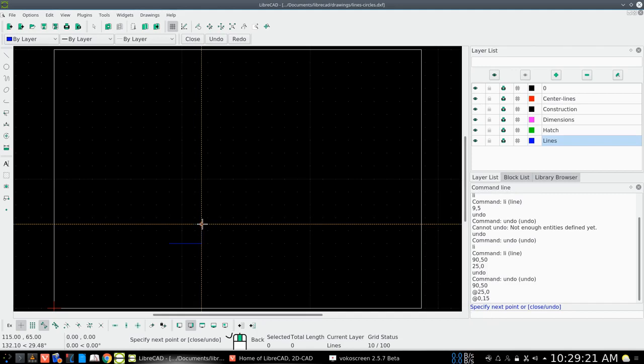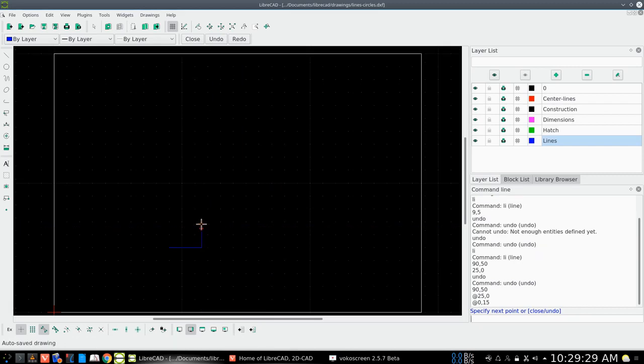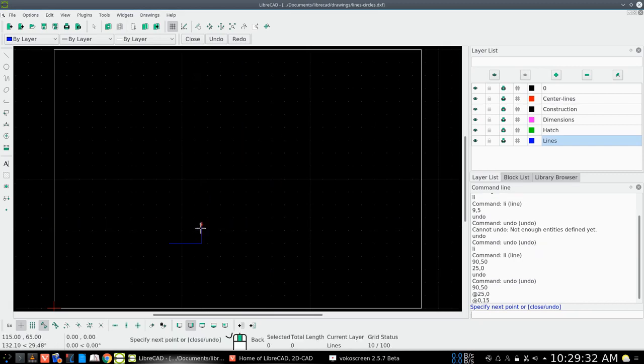Now we want to put a line across here just so we have a datum, a reference line to go with. So what we can do is shoot that line in this direction. Let's go ahead and make relative, and in the X we're going to go, let's say, 60 units and 0 in the Y. Okay, now I'd like to release that tool by pressing the right mouse.